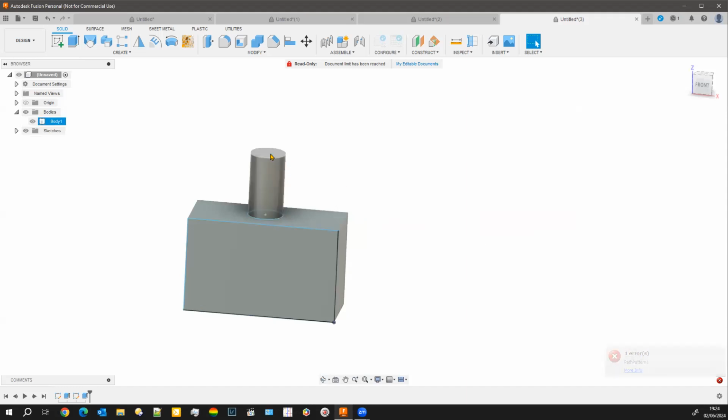It's got no extrusion, there's no depth to it, so it won't actually copy a single face. You have to have sufficient faces to complete a whole, as it were. A little bit like when you're sketching, that if you sketch a box but leave a gap in it, it's an incomplete drawing.